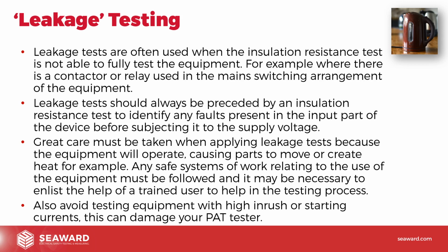Now, that could be okay if it's just something straightforward like a heater: 5 seconds, the elements come on, get the leakage reading, turn it off again, great. But if you've got something like a computer, 5 seconds is probably enough for it to just start booting up, and then you effectively yank the power out of it, and that could cause damage to the equipment.